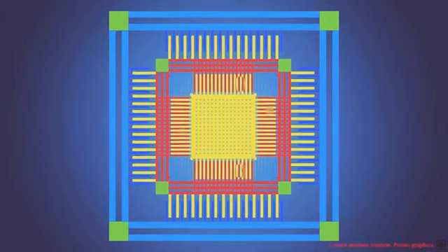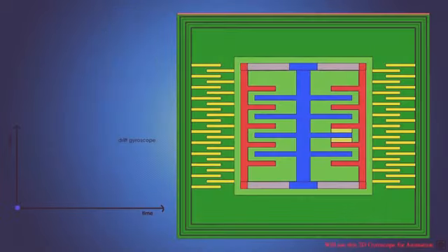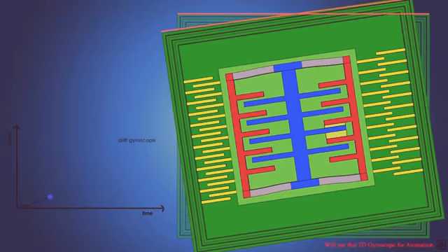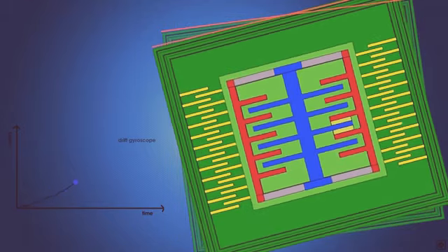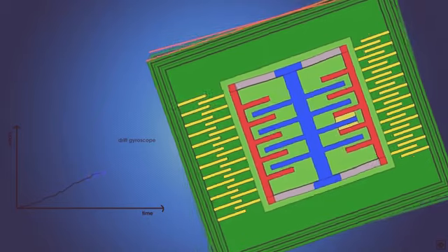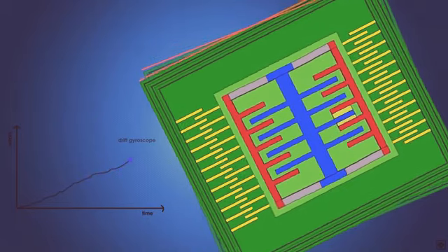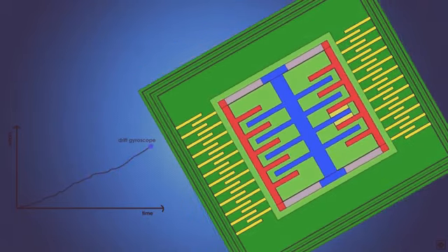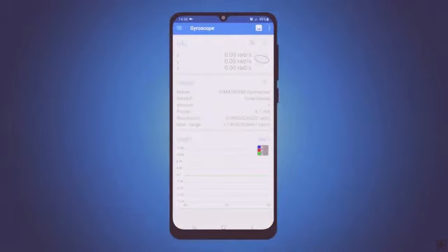So using the gyroscope, the phone can detect how much it has rotated over which axis and process that. But the gyroscope is not affected by gravity, so it has to reference its position on itself. The current rotation is based on the previous rotation added with the detected change in rotation. Over time, errors will add up. Hence, drift will occur. The gyroscope itself is not enough to calculate the true rotation of the phone.